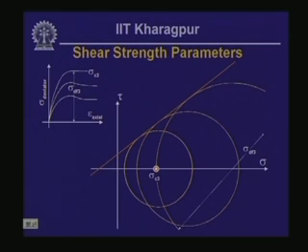So repeating what we said, the Mohr circles corresponding to the three triaxial tests are shown on the tau sigma space at the right of this screen, and now our attempt is to find out what the strength parameters are. You should also notice there is an orange line that is tangential to the three Mohr circles, and that is normally the case.